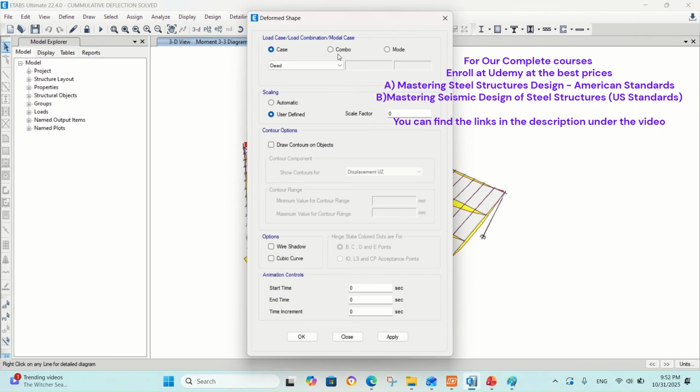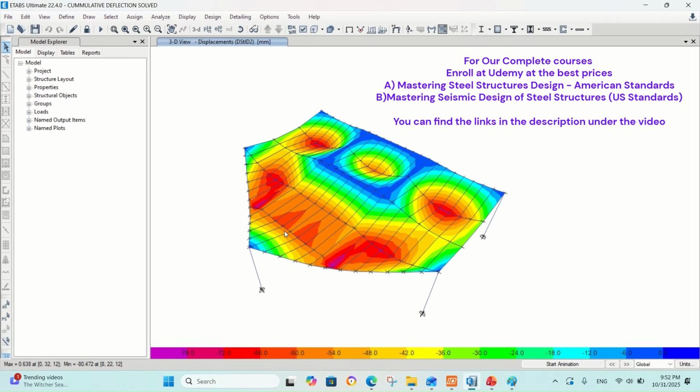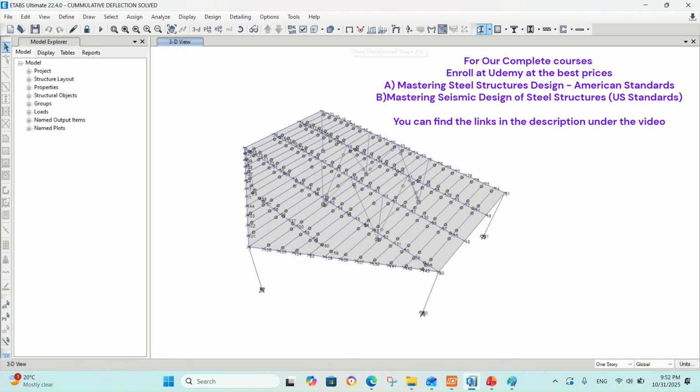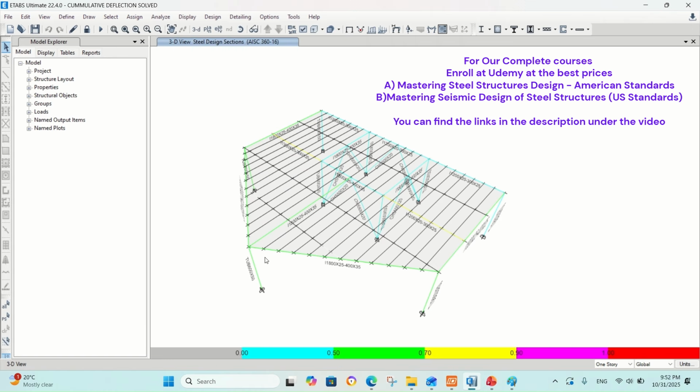To see the total deflection value from the contours, we can see now that this area is not deflecting much, and actually other areas now are deflecting more than this area. However, all the deflection values are within limits. So now my structure is rigid and is well designed. Deflection is within limit, and I can confidently say that I have a safe structure by introducing this main girder.